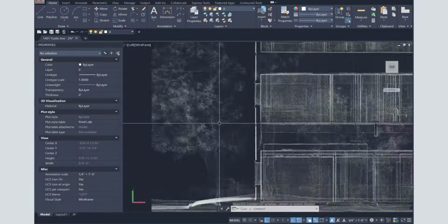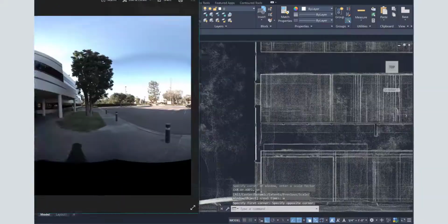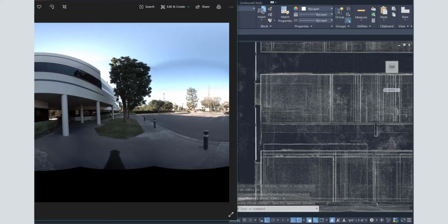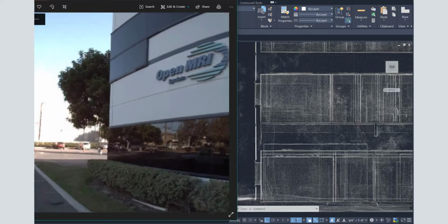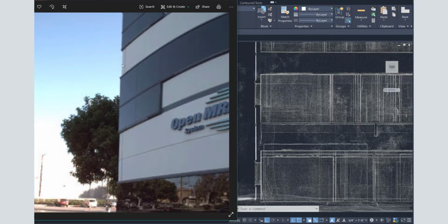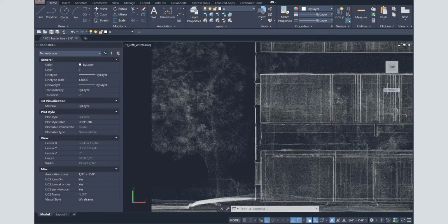When making your crops, you want to have the perimeter pictures open so you can determine what to draft. In this photo, you can see that there is a concrete base with windows on top. In this particular building, the window system actually sits outside of the main perimeter wall. You want to set your crop to include everything on the floor.